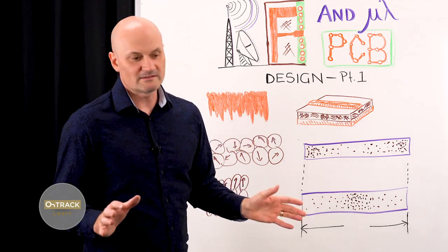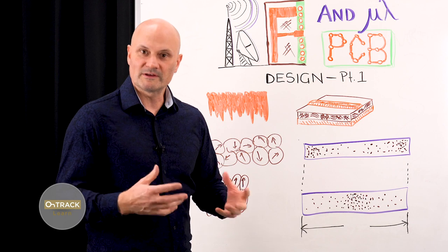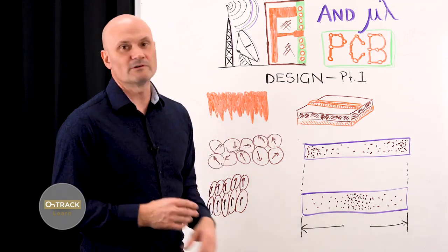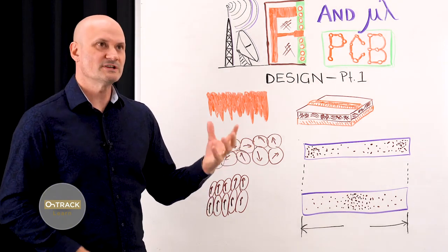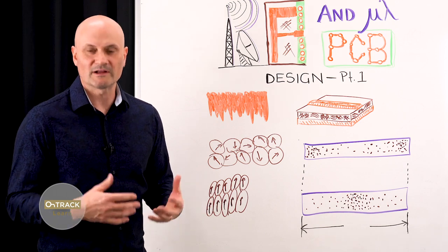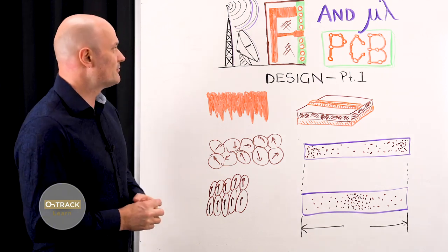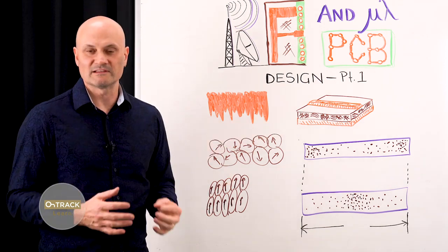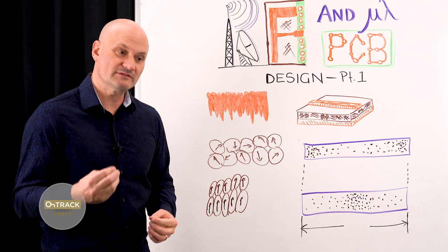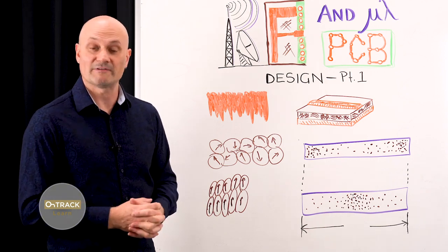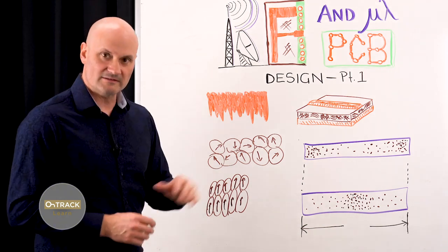The substrate is usually epoxy or some kind of thermosetting plastic material, reinforced with glass fibers, almost always. Some older or cheaper boards use paper, like paper phenolic resin for FR1, and most times recently, FR4 is the most common, cheaply available material, and you can actually do some RF design on a typical FR4 PCB, but you need to know what's going on. So first, let's talk about conductors.